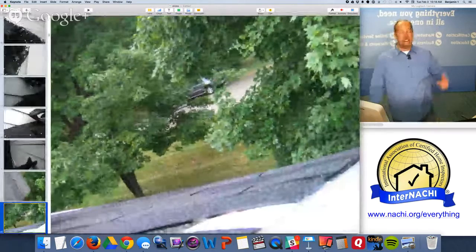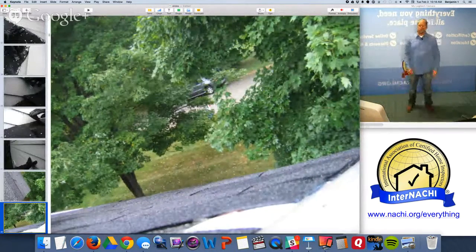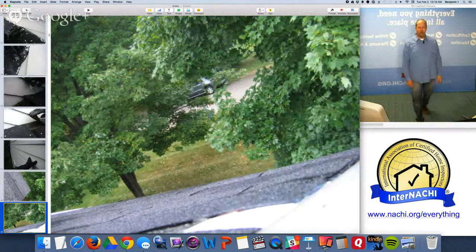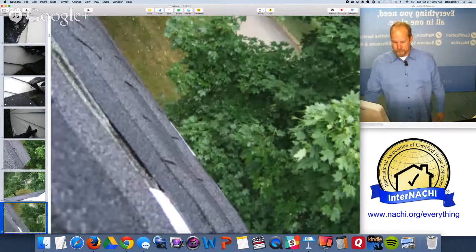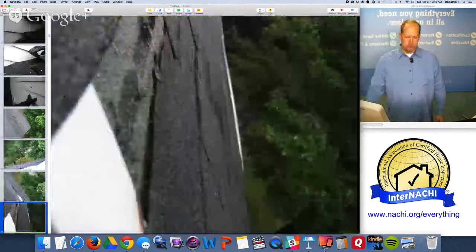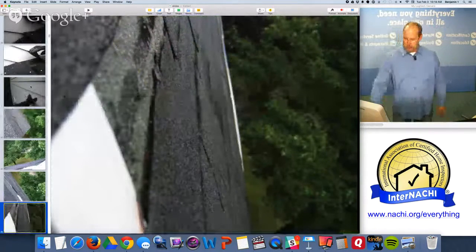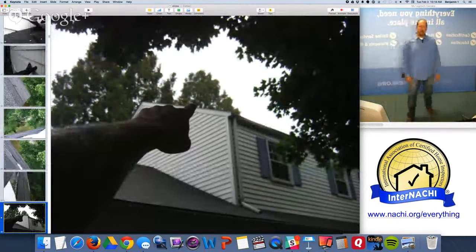And I see, just with my nose above the ridge, above the gable area, the rake board, there's a missing shingle, but I can't take a picture of it. The picture that I like. So that's about as much as I can get, but I can see that it's missing. So when I come down from the roof, I want to point to it, that is the area of that missing shingle. I have a missing shingle at the front left corner of the upper roof plane.